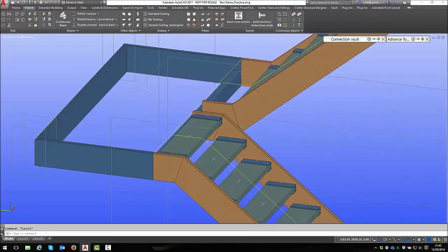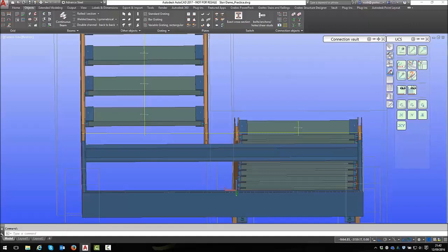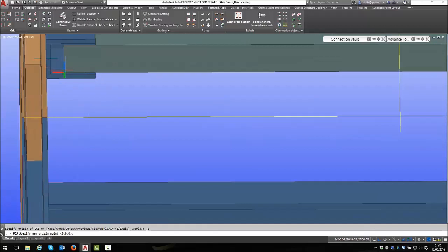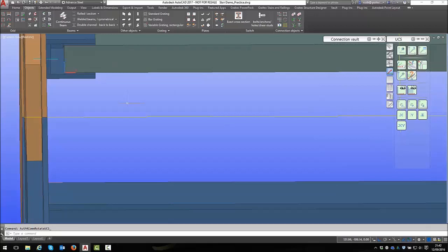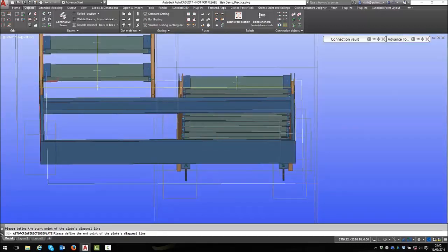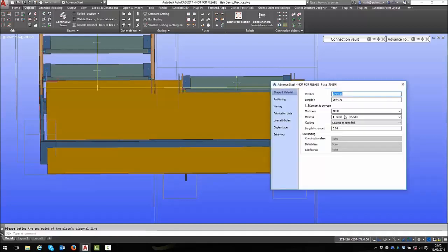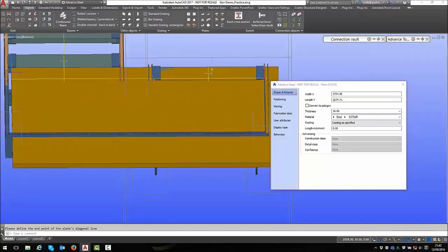Alright, let's sort out the glass panel here. So what I'm going to do, knowing that I need to have my UCS at the insertion point or the height for the glass, let me just rotate this a minute. That's not critical, but nice. I'm going to put my glass from there. I'm going to bring it out here. And it's going to be 50 mil thick. Okay, phase 1. You'll notice same thickness now as the tread.